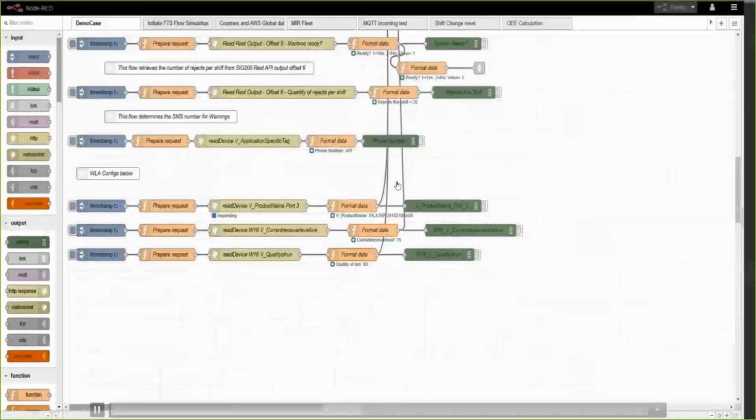Now, if you look, get the laser pointer up. If you look here at this receiver level, that receiver level next to the pointer, that was what we were looking at in the REST API window. So it was around about 72, 73. In this situation now, it's sitting at 76. But you can see the quality of run below it, we're getting a local bit of information out. That was dropping. Well, I've just removed the bit of plastic contamination, and we can see the quality of run is going back up. Not as quickly as the receiver level, because that's shot up back to 98. But the quality of run is tracking back up.